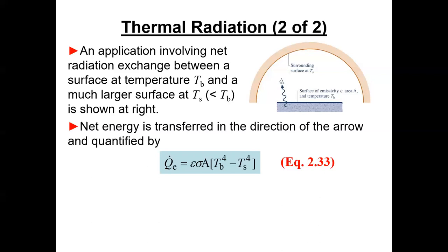Now, the other thing, which is not in here, which you get into in the radiation course, which is pretty complicated, is a view factor. And they don't even mention it in the book. A view factor talks about, say, if you want the net radiation from that slab surface, then you have to be concerned with all of the different surfaces that slab can see, because it can radiate to anything it can see.